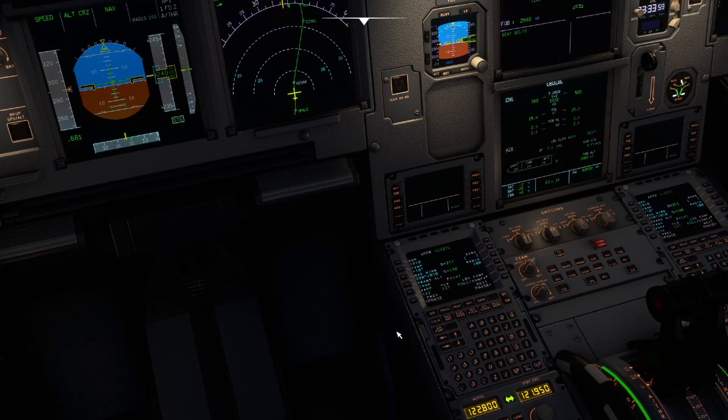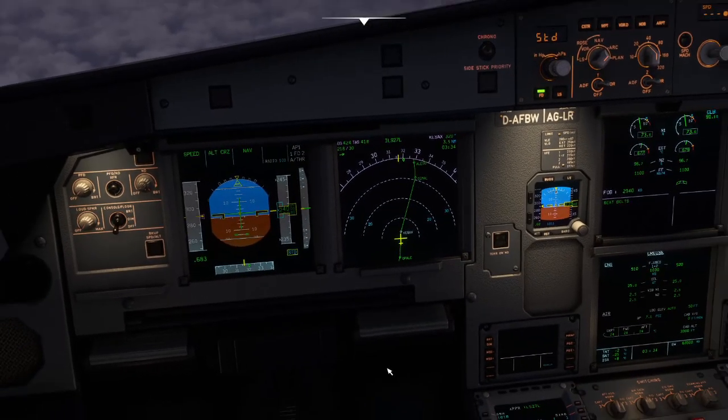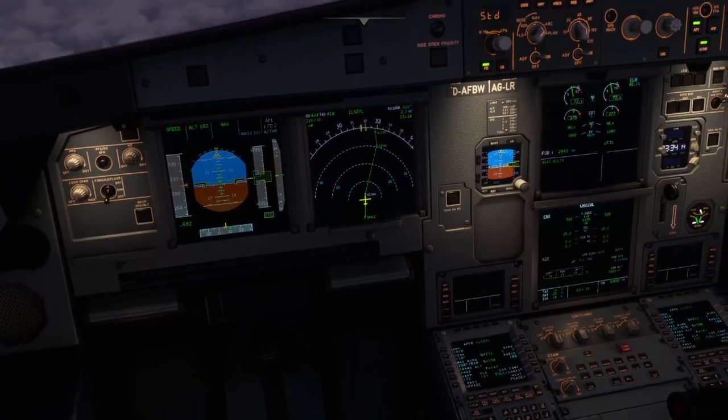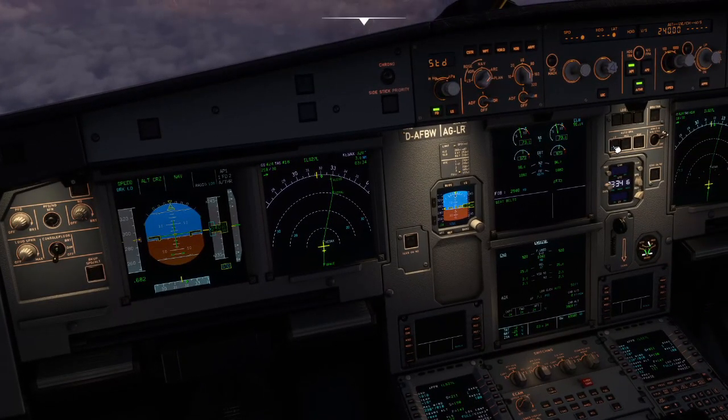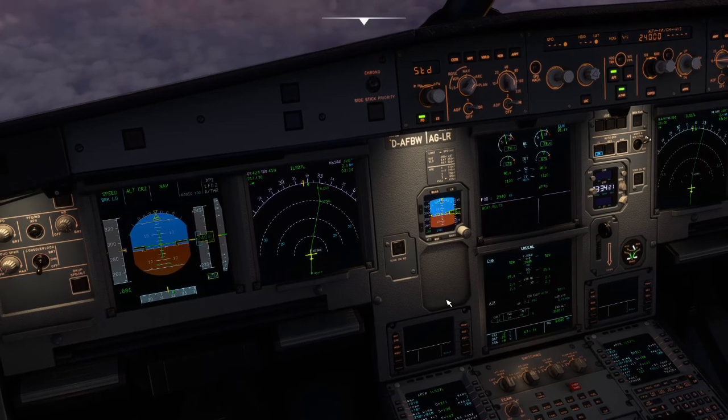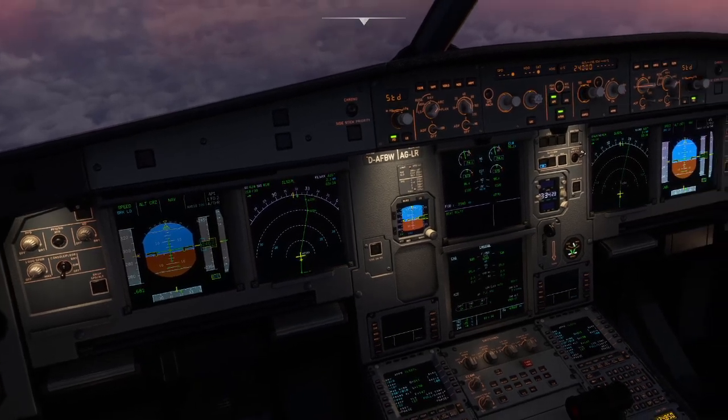If you've got stronger winds than that, by all means, you could plug in some slightly higher numbers, and the autothrottle is going to hold that for you. It's a good baseline. So 10 knot wind day though, happy with just a 5 knot additive on 132. That's pretty much me prepped. Massive runway, auto brake low. We don't really need auto brakes at all, but it's a good habit to be in to at least think of the auto brakes at this point.